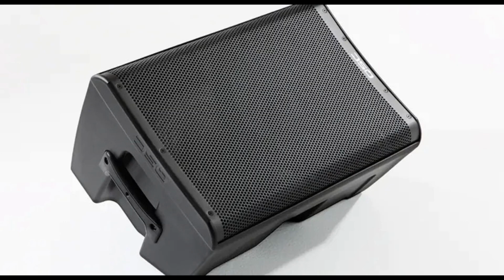And I need to make sure and choose this box specifically in the prediction software because the weights are different than the passive version of these boxes. I had 8 QSC CP8s for front fills, foldback if I needed them. And my console was an M32 and had a DL32 stage box that was going to sit behind the stage. I did not have an external DSP, so any speaker processing needed to come from the console. And I had two QSC KW181 subs.